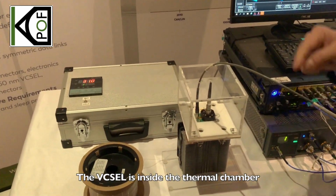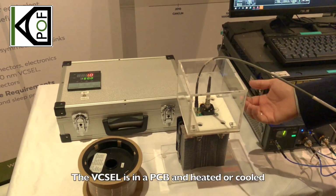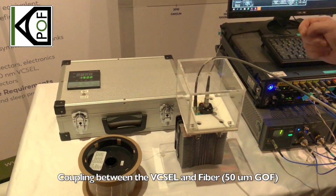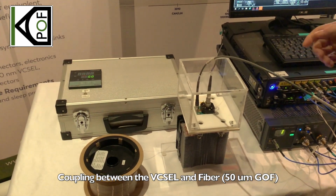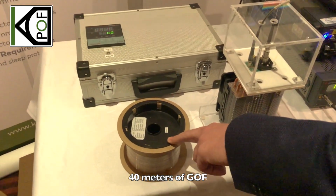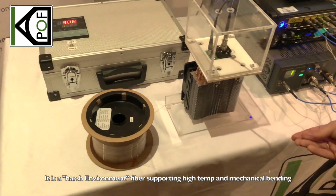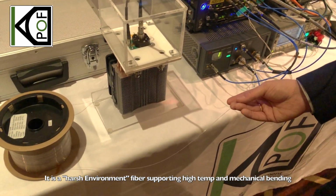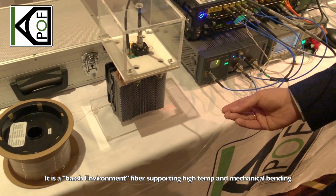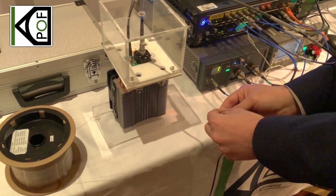In this chamber you can see a PCB where we do the transition between the coax and the pixel. The pixel is behind the optical stage that we use to couple the light into the 50 micron graded index glass optical fiber. After this coupling, we have 40 meters of this fiber. The fiber is a graded index glass fiber that is able to operate in harsh environment between 60 and 200 Celsius degrees, as you can see, with very, very good mechanical strength properties.